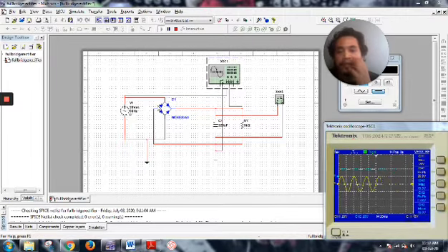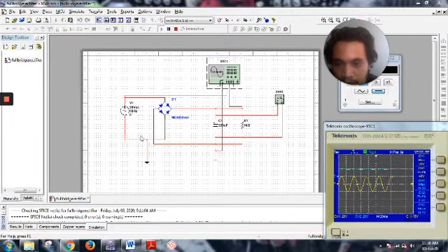And in the negative phase of the AC current, the negative part goes to D3 and D4. So D3 and D4 are in series, and D1 and D2 are in reverse bias.